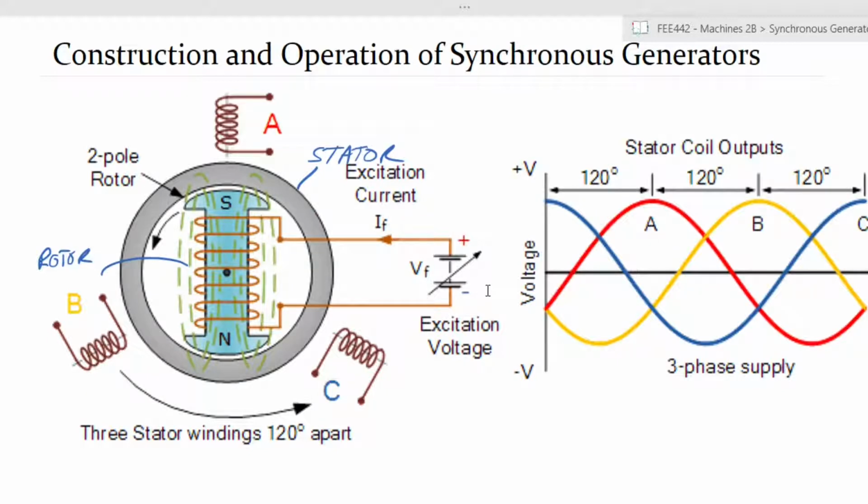So as you've seen from the animation, which I will share the video, the rotor is a magnet that is placed inside the stator and it is free to rotate. We call the rotor the field windings because it is supplied, as you had seen from the animation, with a DC field, and that produces a magnet with two poles, or in the case of that animation, 4 poles. So the field is in the rotor, and the stator now contains the armature